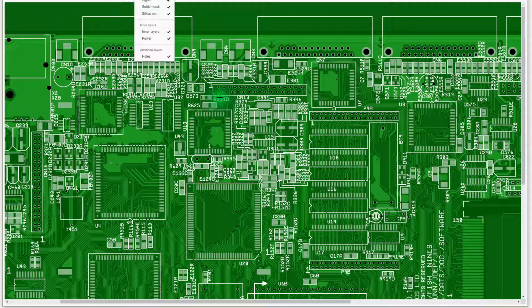The other thing this gives me a really good look at is the connector here for the flex cable from the keyboard. And I've seen a few forum entries that talk about how close the solder pad is here to this connector. I don't honestly know if I'm going to be able to get even a fine tip soldering pencil in here to unsolder this without touching this connector. I don't want to melt the plastic in this connector and deform it. That could cause issues with the keyboard not connecting correctly.